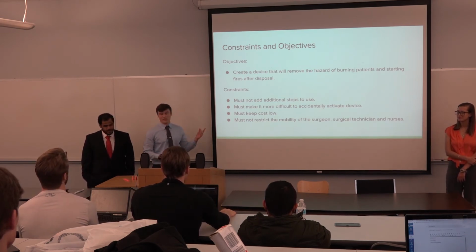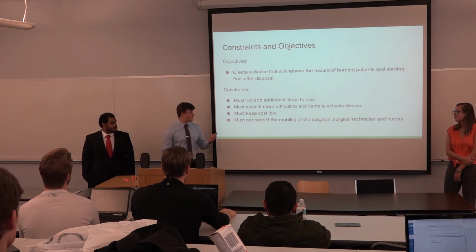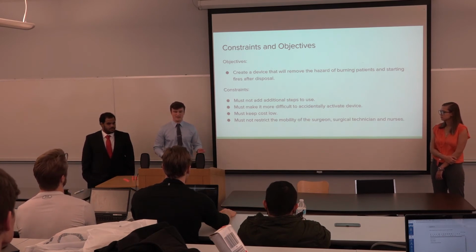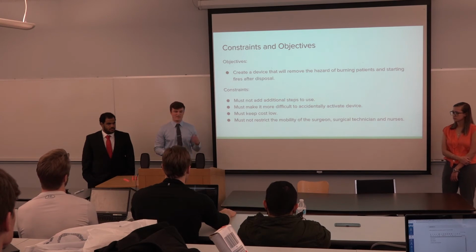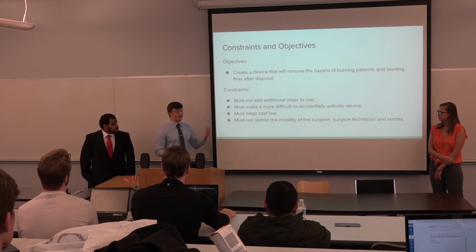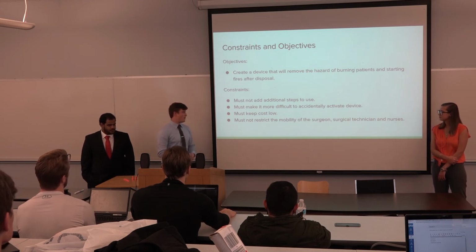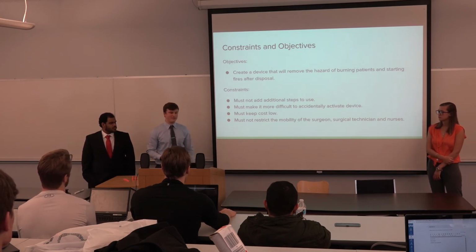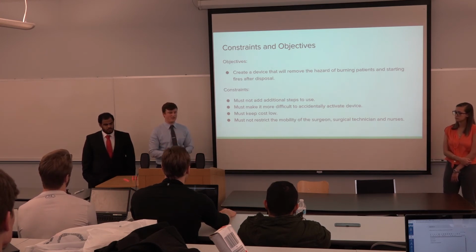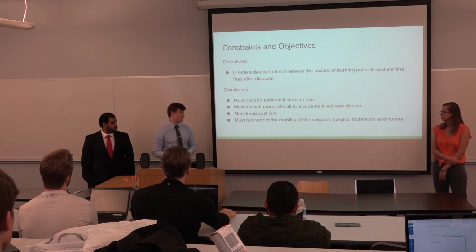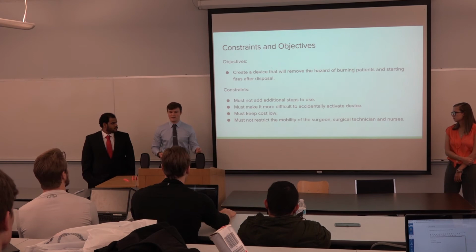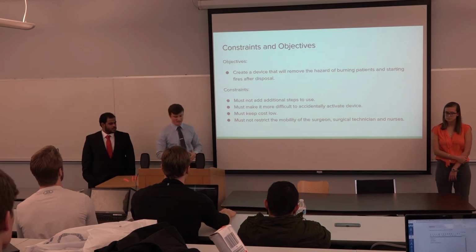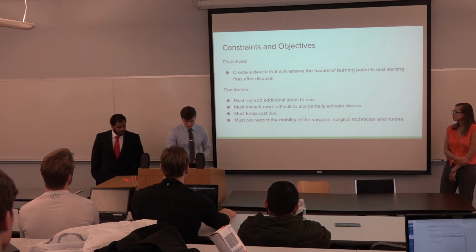Some of our constraints from our expert interviews were that it must not add additional steps or make it harder to use, because the surgeons have been using these for years, and during surgery, oftentimes they're tight on time. So we didn't want to add an additional learning curve to that. It must make it more difficult to activate the device accidentally. So if you throw it in the garbage, you don't want a piece of trash pushing on that button and turning it on. And it must not restrict the mobility of the surgeon, just because oftentimes they have to be pretty accurate with where they're touching it because it gets really hot. You don't want to burn them in different areas.